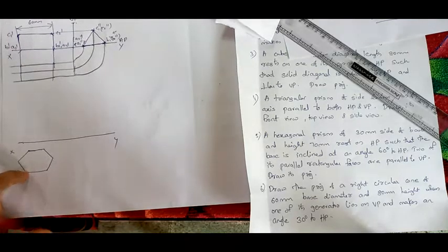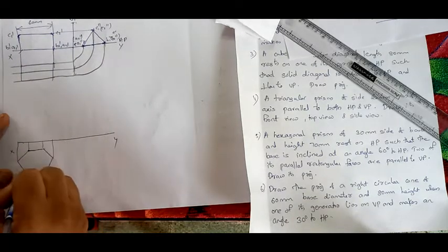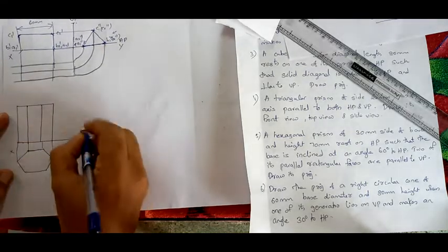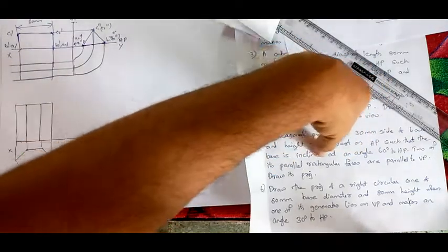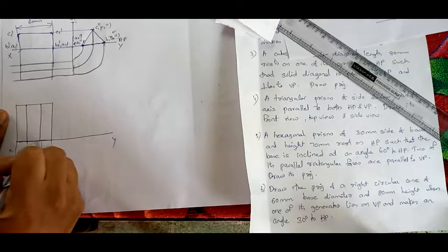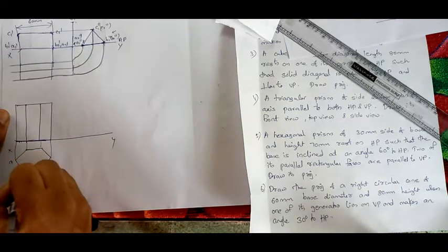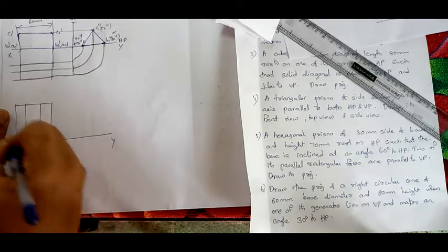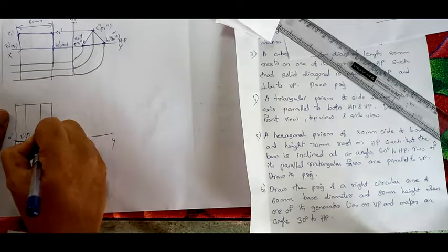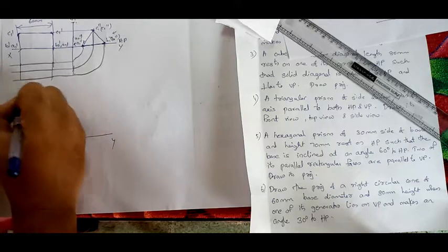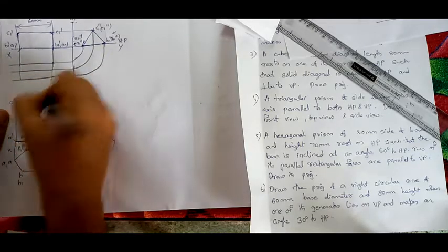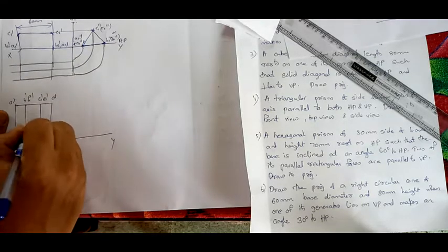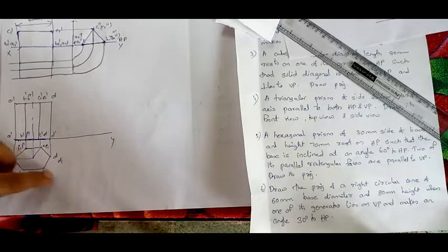See, I have placed the hexagon like this. Now I will find the corresponding front view, it will be like this. Now they have told that the base is inclined at an angle 60 degrees. So this is your base, and these two are your bases. If it is A, B, C, D, E, F, and A1, B1, C1, D1, E1, F1, then this will be A dash, B dash, F dash, C dash, E dash, D dash. Here A1 dash, B1 dash, F1 dash, C1 dash, E1 dash, and D1 dash, like this. And the axis, you have to find the axis, it will be like this. For a prism, you don't need to cross all the diagonals.